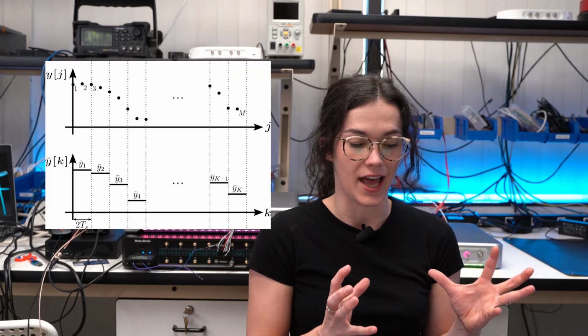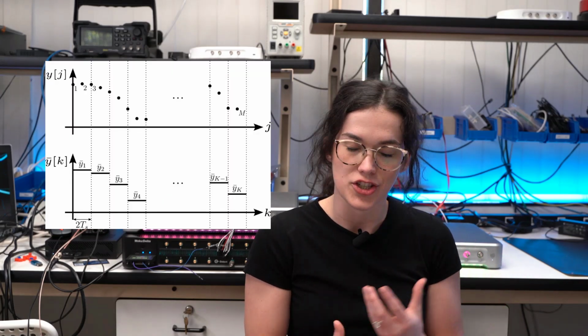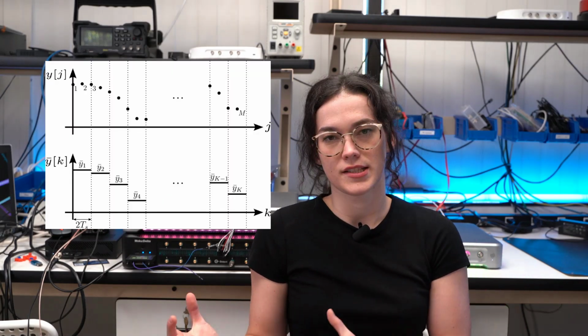The basic principle of Allan variance is to divide a time series into sections of equal duration. And then we want to consider how the time average of each section compares to that from a previous section. If these differences are small, then the system is overall stable on this timescale. And then Allan deviation is the square root of Allan variance, much like standard deviation is the square root of standard variance.